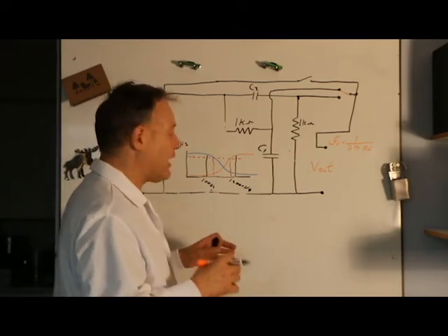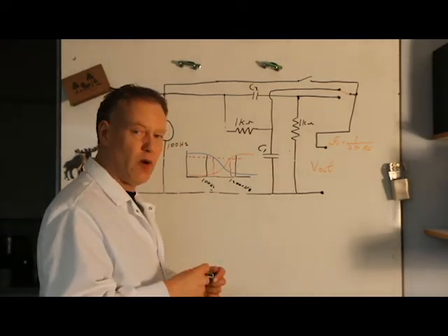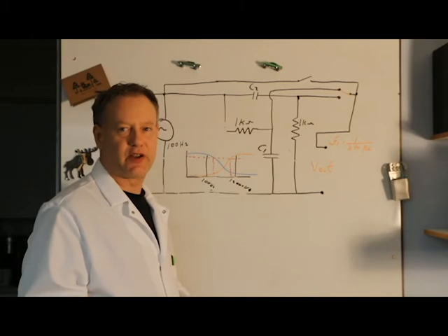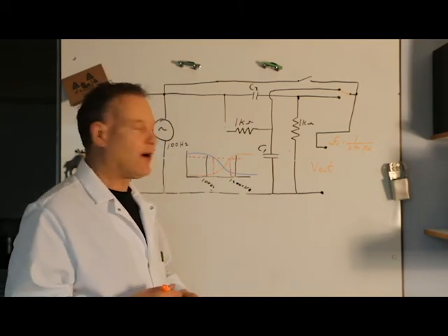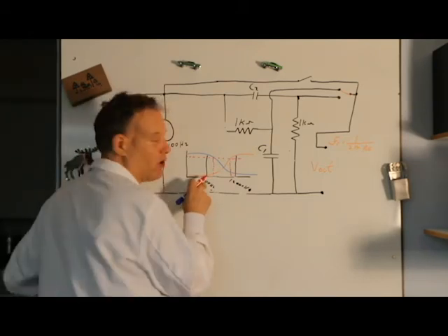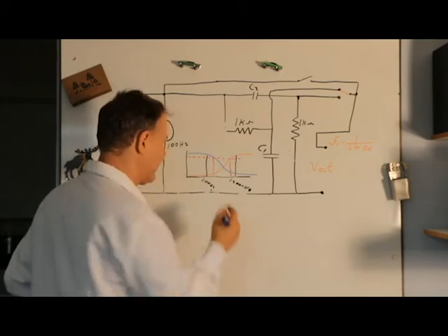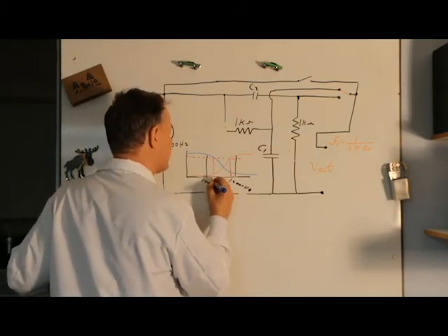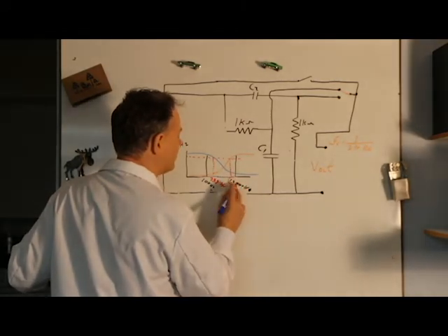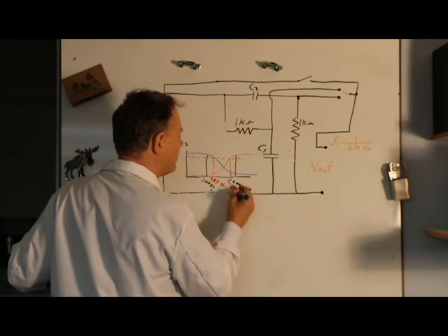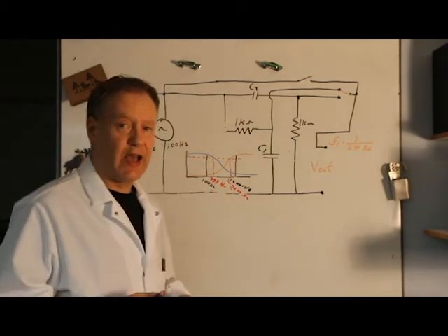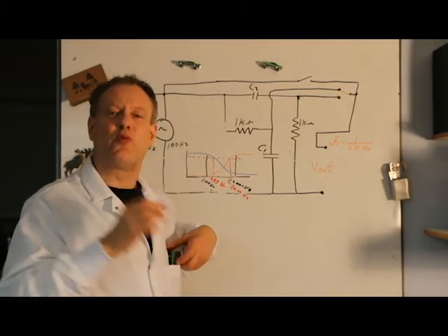Okay, good. What I need to do now is figure out what my corner frequencies are, because I'm designing my circuit and I have to figure out what the capacitors are, and they will define my corner frequencies. I need a corner frequency right here that is a little bit past 100. Let's go for 333. So let's say this is 333 hertz, and this guy, let's make this 7200 hertz.